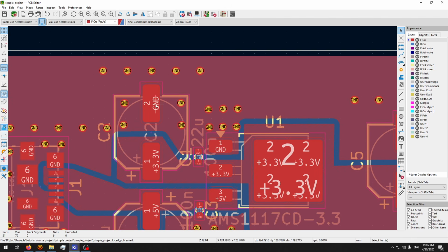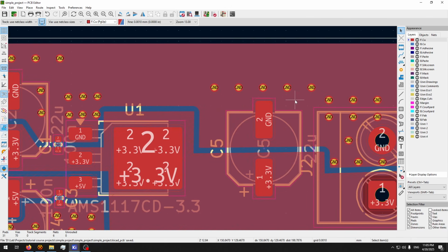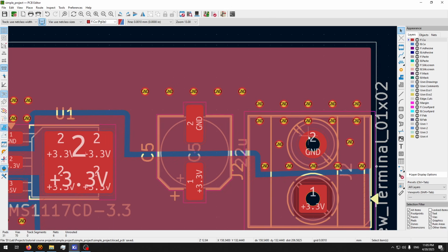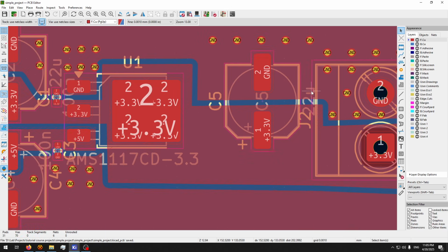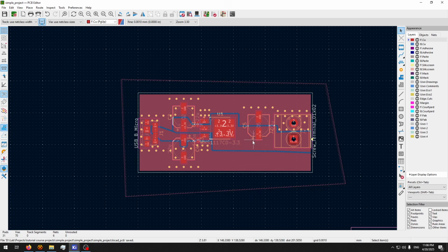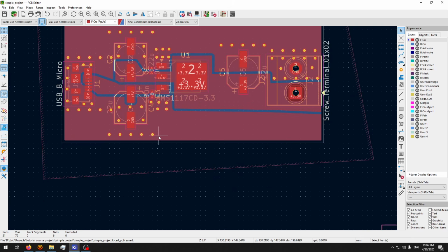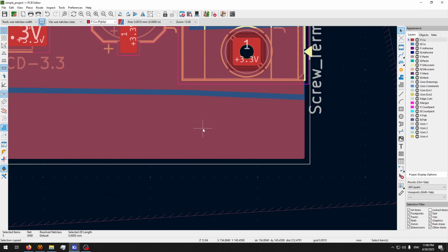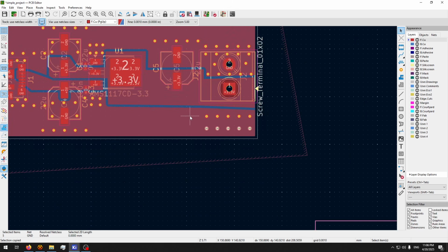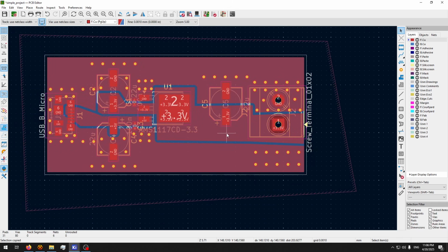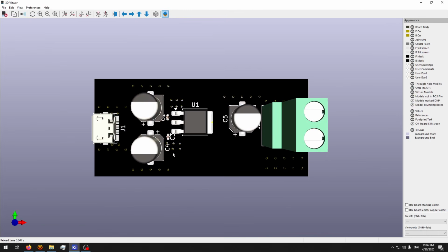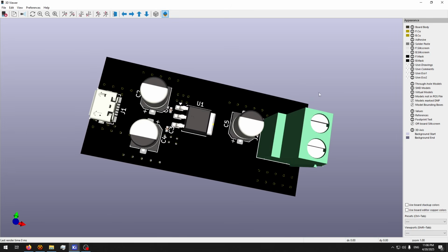Now since we have surface mount, only one layer is just enough for that, but it's always better to have 2 layers, ground pours everywhere, stitched everywhere. For example, this area right here is not really connected. Let's stitch it out. Very nice. And let's say that we are satisfied with that. Control S, Alt 3, and this is our design.